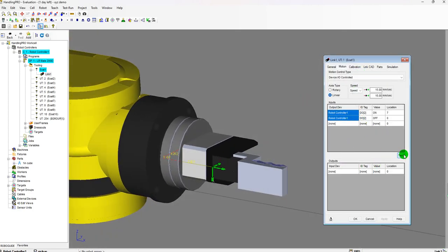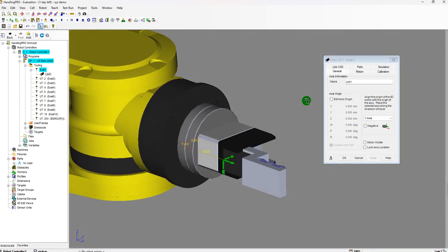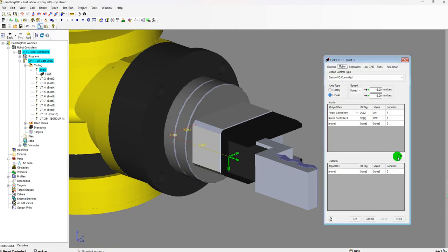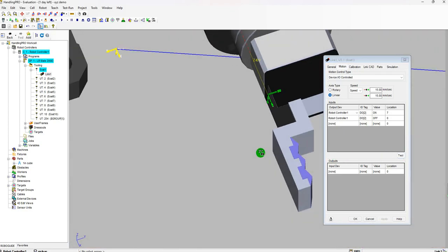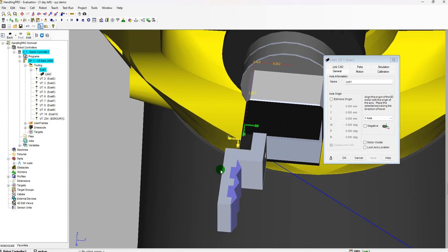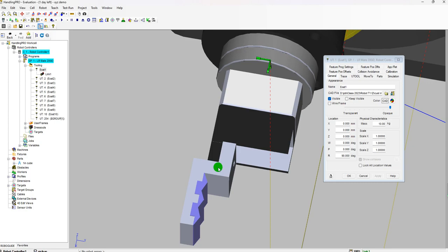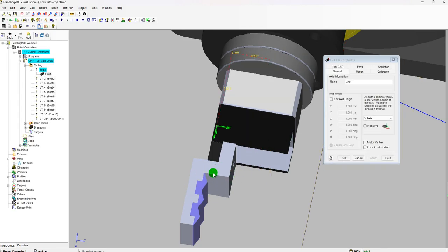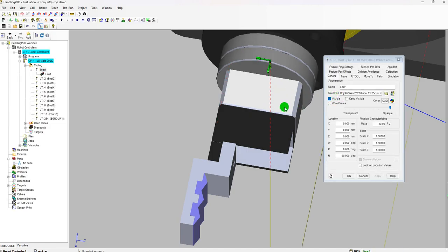When I test it, it's along the Y orientation. What happened, right? We wanted it to move along the Y orientation. No, it moves around the X axis. Correct myself: it's not along the Y direction, but the X direction. Why? Because for the X, Y here, you don't want to reference the jaw's coordinate system, but the base, because this is a part of the U2. So we want to set up this jaw based on the U2's coordinates, or UT end of arm 2.